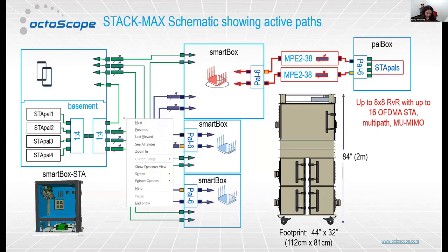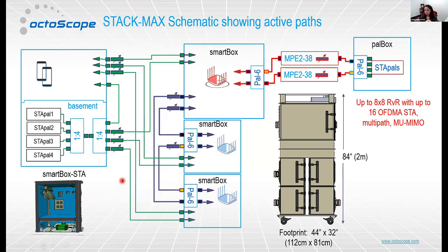different rooms, right? But to Lee's point, if it's a dipole antenna, it has a certain field, so the field will differ, but in the end, it's a multipath environment, and when the signal bounces, the polarization will change as it bounces off. So MIMO is a very dynamic environment, and the antennas on the device on one floor with reflections from another will still have to pick it up in their field, which for a dipole is like a donut field. So this still has to reflect and get into it. So with the multipath, I would say you're covering some of those scenarios.